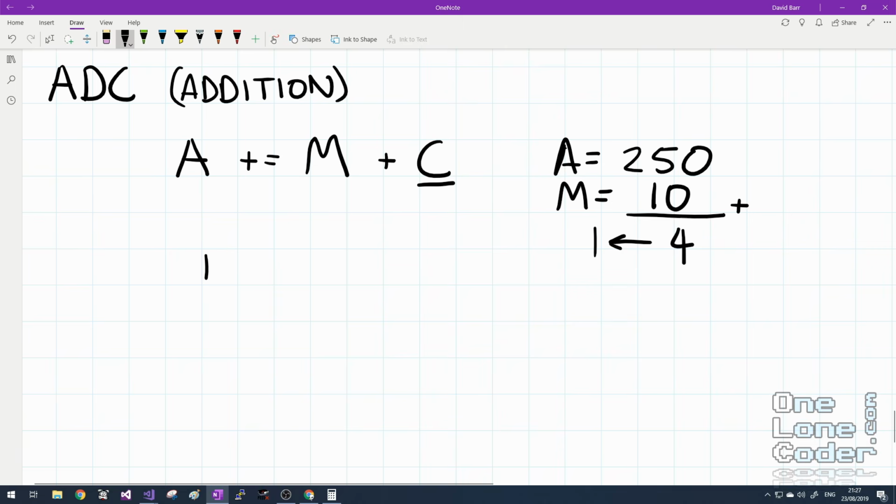And if I was working with 16-bit numbers, which I can't store on the 6502, I can algorithmically add them by looking at them in 8-bit parts. So if I add the 2 low bytes together, which are both 8 bits, that's fine, that gives me some answer, but that has the potential to spit out a carry bit, which I then need to add to the 2 high bytes when I add those together.